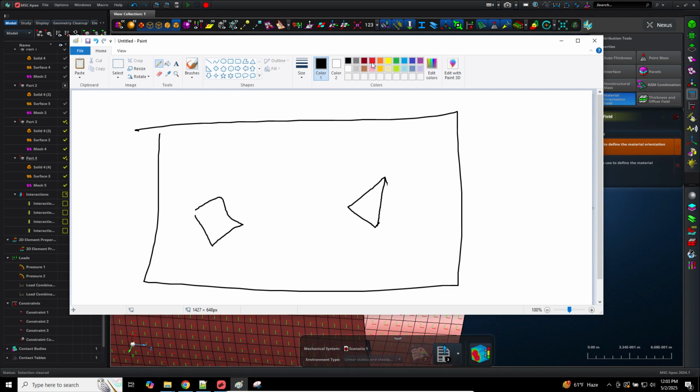Remember that there's an element coordinate system, and by default, the material coordinate system is parallel, which is not good. So this is XM, YM, and this is very important when you look at your applied stresses and applied strains, because those will also be bad. This is completely wrong in my opinion.